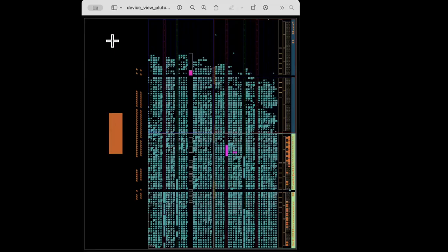But our custom code is kind of a lot. So we put our custom modem into the reference design, and when I say reference design, this is the basic software radio from Analog Devices provided for the 7010 on the Pluto SDR. This is the smallest of all of the dev boards that we work with, because we also work with some 7045s or 7100s and some UltraScales, which are much larger. You can see that with all of the reference design, essentially the overhead or infrastructure that has to be in the FPGA for the Pluto SDR to work, we've added our code and we still have some headroom here.